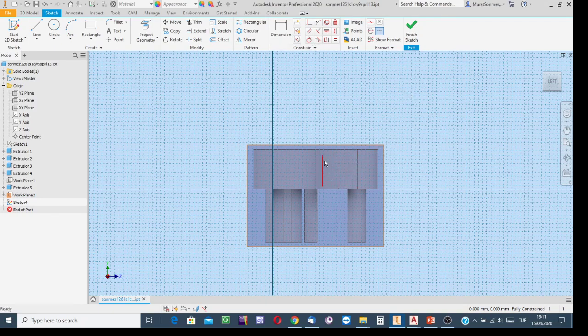And then yes, I'm going to create the opening relative to the surface of the floor. So apply the project geometry process, have it as an image, the image of the edge of the floor, of course, and the other reference will be this limiting surface of the cylindrical surface indicated, and then say that the opening is a rectangular opening.